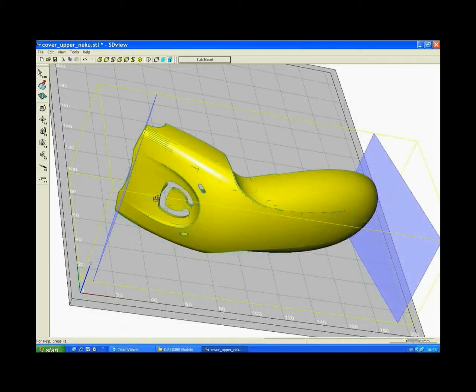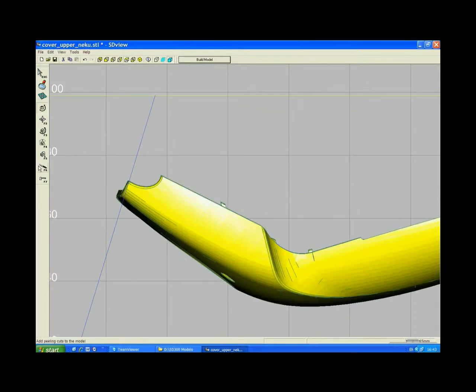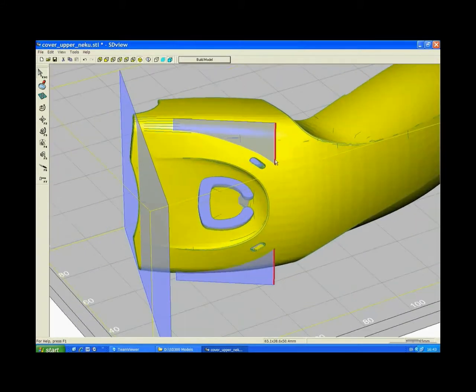We will now close the following openings on the X and Y axes. We will drag a peeling cut in the area of the openings. Then, in perspective view, we can modify the peeling cut so it reaches all openings and lower the top edge and bring the bottom edge up.